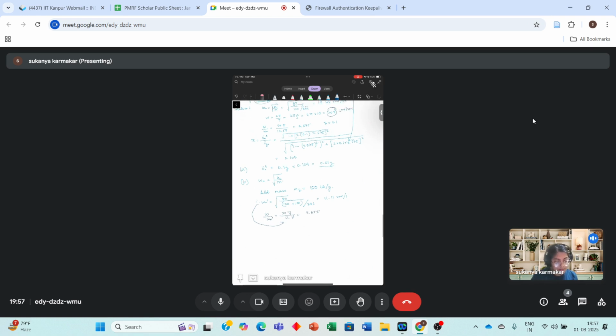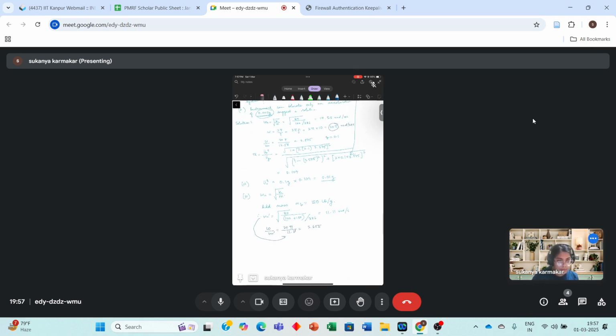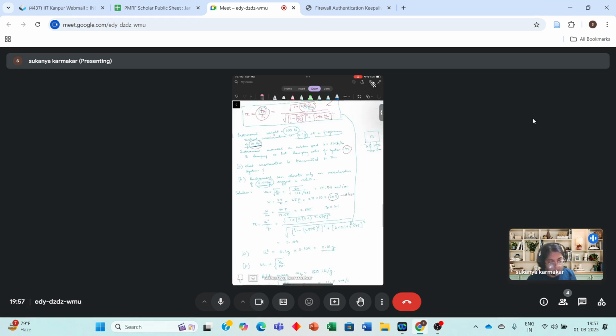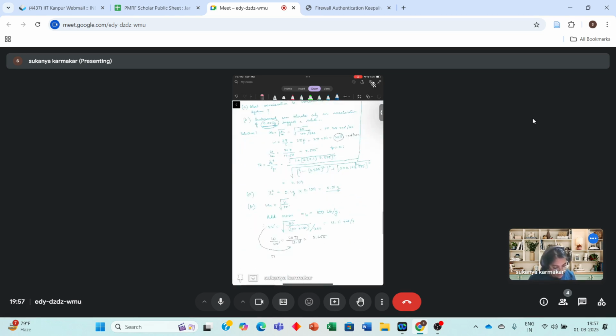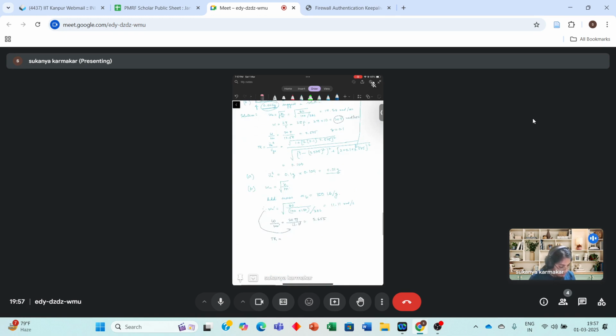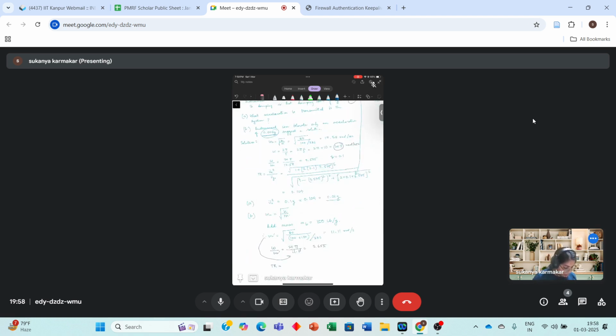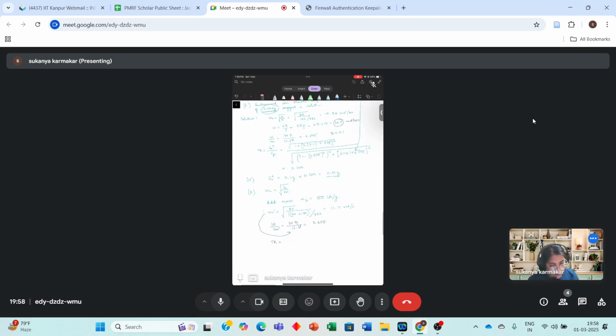Now using this new omega by omega n dash, you can calculate again this transmissibility. And when you do that, you will find that this ratio has gone down also. Apart from this, you will also need the new damping ratio.